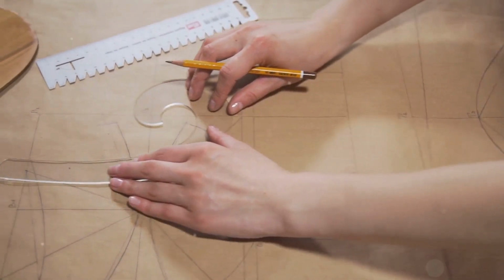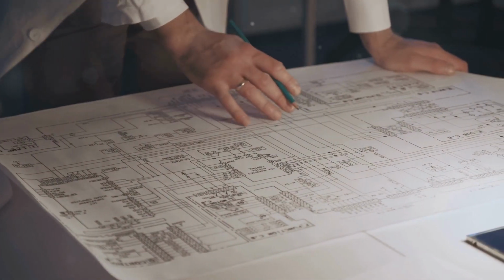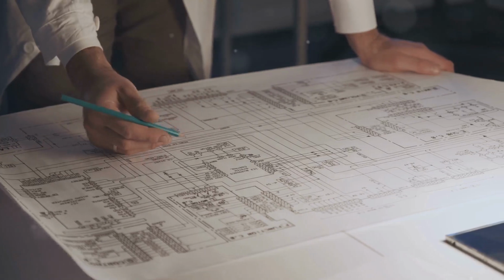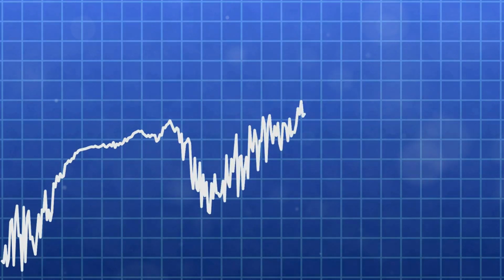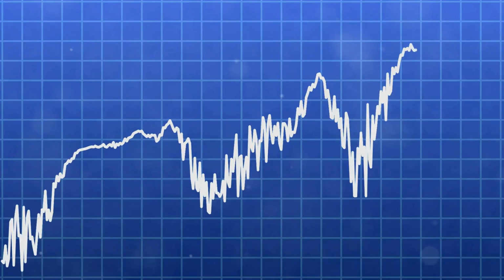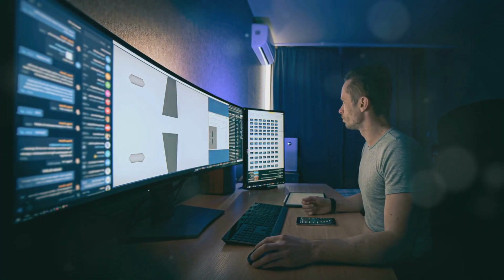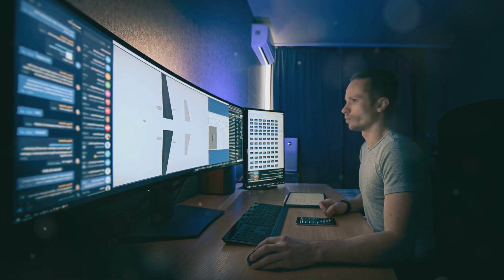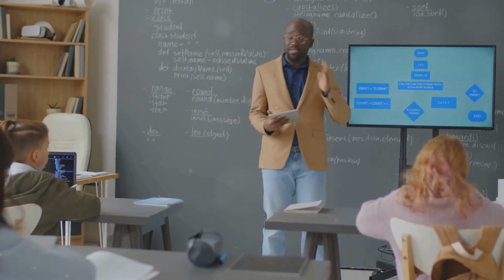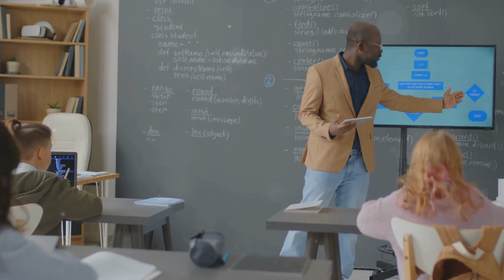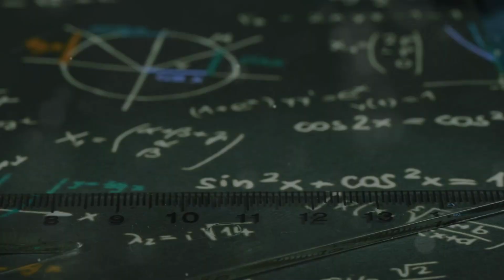While pole placement offers direct control over pole locations, it can be challenging to translate performance specifications into specific placements. LQR provides a systematic way to find the control law that minimizes the defined cost function, often resulting in a more balanced control strategy. However, LQR requires a well-defined cost function and can be computationally demanding. The choice between LQR and pole placement depends on the application, performance criteria, and the engineer's familiarity with each method.